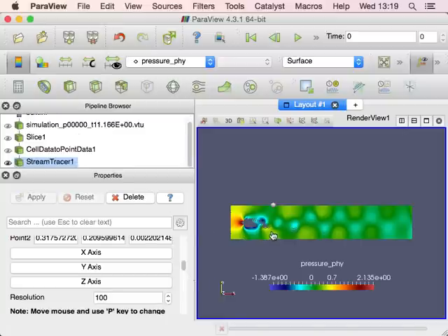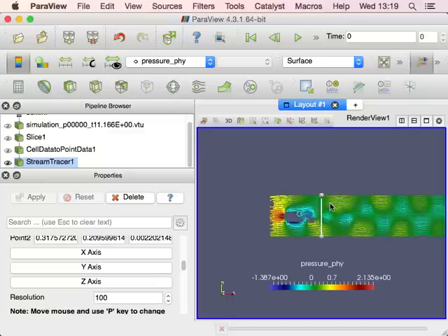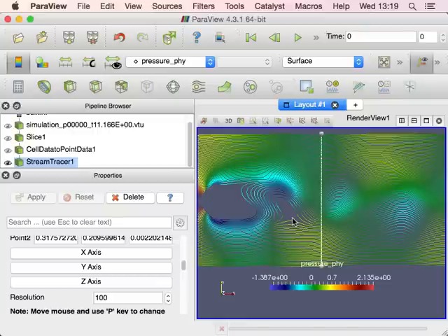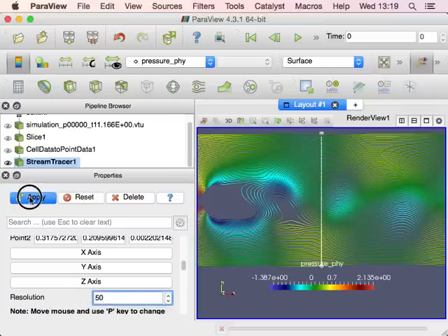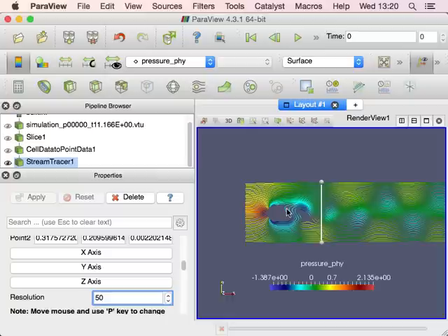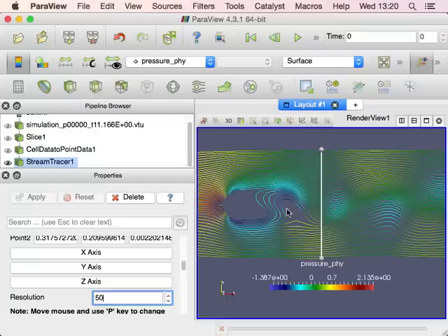So okay, let me zoom in a little bit. It's actually becoming lines and not voxels anymore. I chose 100 lines, so maybe I decrease this number, you get a better view. Yeah. So in this case, the whole domain is represented by streamlines. By streamlines, we can get a better idea of how the fluid is flowing from inlet to outlet.